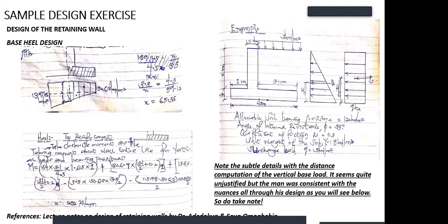Can you answer that? Vertical. Obviously, it did not change. So what is basically taking moments there is your vertical force. So all vertical forces are taking moments. So the weight of the base itself is a vertical force. Are you with me? The weight of the base itself is a vertical force acting at this particular center.